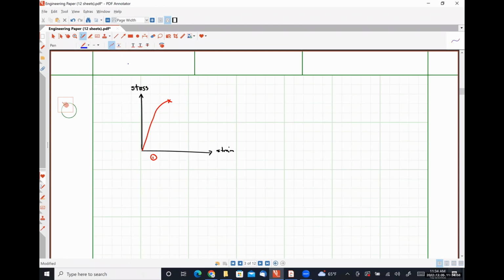So for something like that, if we put a beam in our measurement apparatus, we would find that it just breaks, but you could actually put it back together like a puzzle to restore the original shape. Okay. Glass is a brittle material. Silicon is a brittle material. Okay, so we're going to expect that we have to design such that we don't want any permanent mechanical deformations to occur.